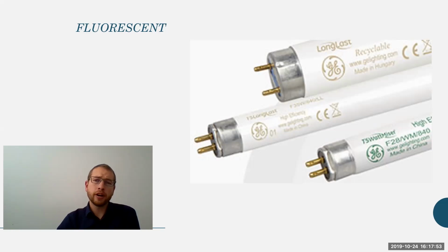What you will find a lot of are T8s, and those can range in efficiency, but pretty much any T8 is better than a T12, and T12s are rapidly being replaced. I don't think they're allowed by code anymore, but you might be able to find them at Habitat for Humanity or a Second Chance store because people are trying to get rid of them because they're no longer useful in new buildings. So that's one thing to be aware of.